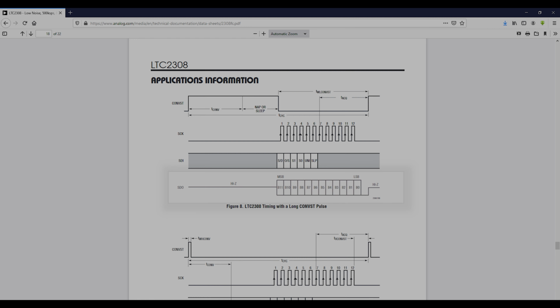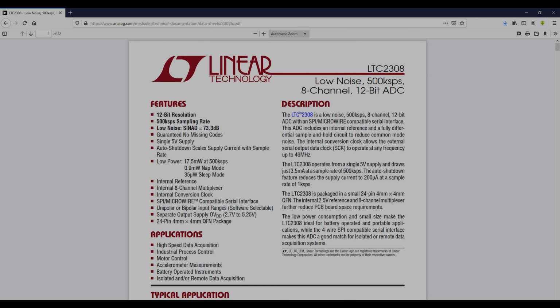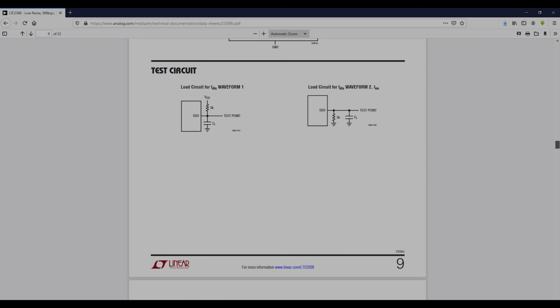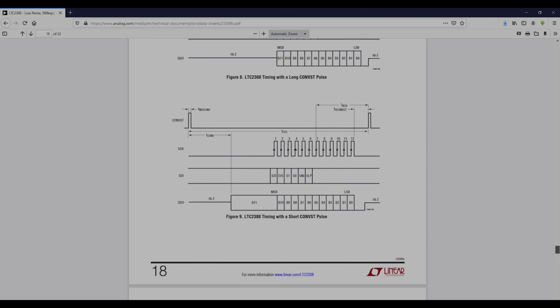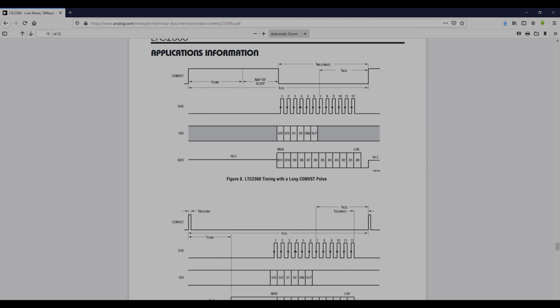Okay, now the S clock, we can see that the maximum S clock that we can have is 40 megahertz, and that's significantly faster than our maximum sampling rate, because we need many S clocks per cycle. In our interface code we will have to produce a cycle like this and make these things happen once every cycle, and we can take 1 sample per cycle and move it to the next stage